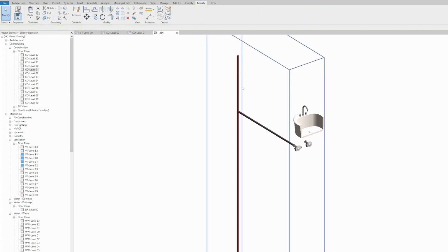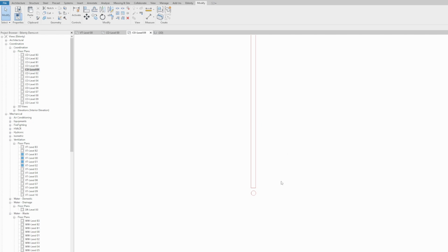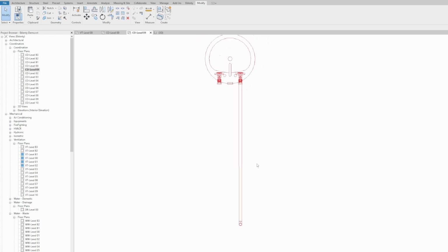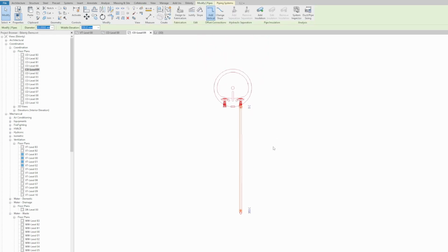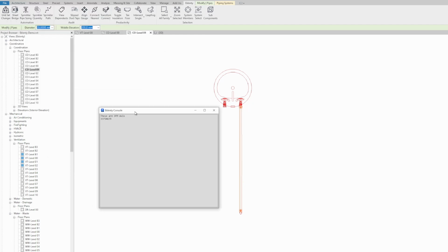Let's extend this pipe first. You won't be able to connect this to the main pipe, right? And in this kind of situation, people tend to use the tab key. People simply drag and they see it won't connect and they simply hit the tab key. And this causes inaccuracies as well. Let's see that. As you can see, it reports these are off axis.